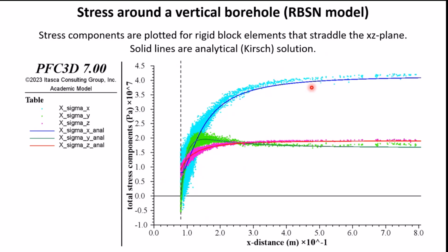So basically, I'm very interested in your crack propagation analysis, and I did some work on that before. Based on my understanding, there are two challenges for crack propagation analysis. First, for conventional finite element, it's very hard to capture the stress field at the crack tip because it's an asymptotic distribution, and the shape function of the conventional finite element is polynomial.